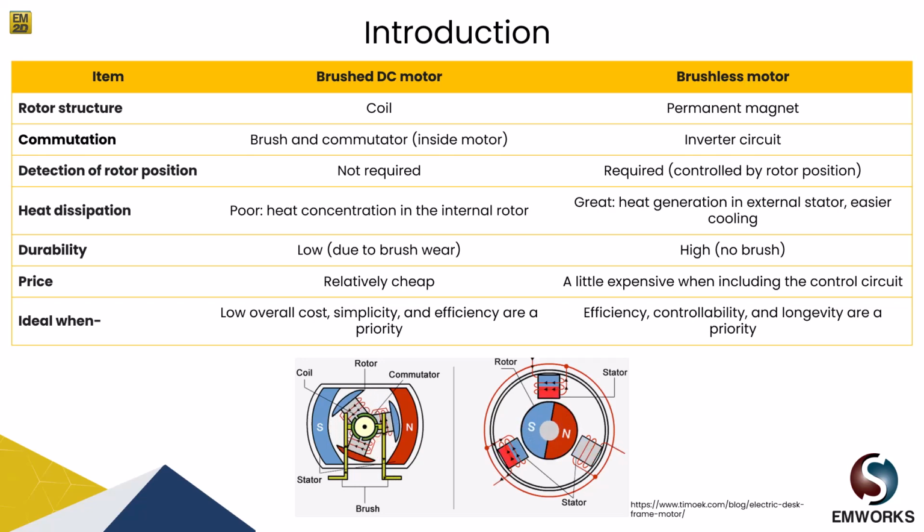since the brushless DC motor doesn't have any brushes and the rotors are mounted with magnets, it has more reliability compared to the brushed DC motor, whereas brushes get wear and tear over a period of usage. In terms of price, I think the brushless motor will be a little expensive because it needs a drive circuit to run or to drive the brushless motor.